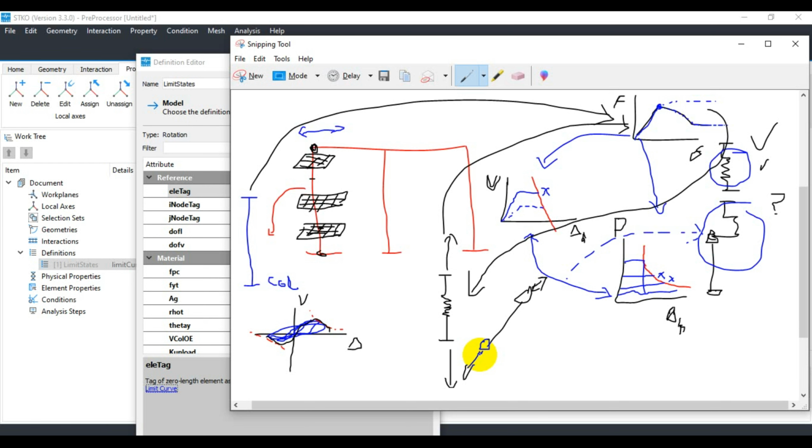In this lecture, the uniaxial material models that I am going to discuss are already available in OpenSees, starting with the hysteretic material model. It has a predefined trilinear or bilinear backbone curve and some parameters to define the hysteresis behavior.